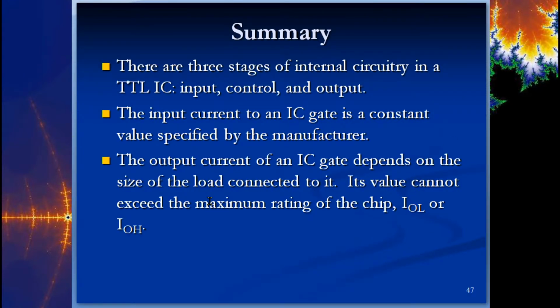Okay, so just to summarize all of Chapter 9. It says there are 3 stages of internal circuitry of a TTL IC. We didn't really cover that because I don't want you to get down into those woods. Input, control, output. I just want you to get under your belt the notion of sinking the current through that bottom transistor versus sourcing it out in the top transistor. Okay.